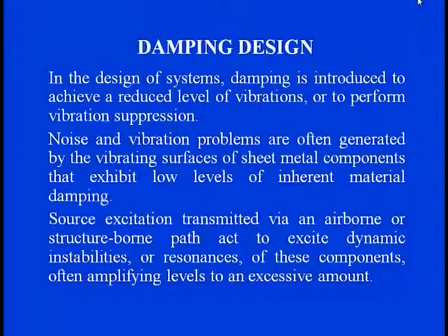So, when we are trying to design the damping, we know that damping is basically the reduction of vibration excitation. We need to suppress the vibration. Often the sheet material, which is always there as part of the product design, provides a good domain for the transmission of vibrations because of the low level of inherent material damping.